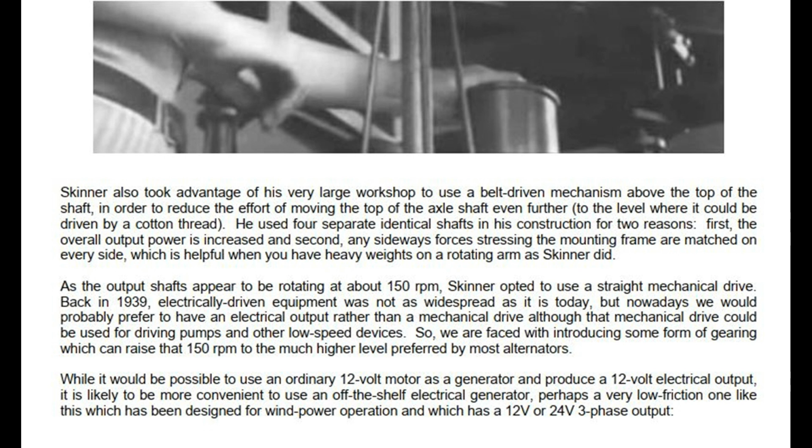He used 4 separate identical shafts in his construction for 2 reasons. First, the overall output power is increased, and second, any sideways forces stressing the mounting frame are matched on every side, which is helpful when you have heavy weights on a rotating arm, as Skinner did. As the output shafts appear to be rotating at about 150 rpm, Skinner opted to use a straight mechanical drive.